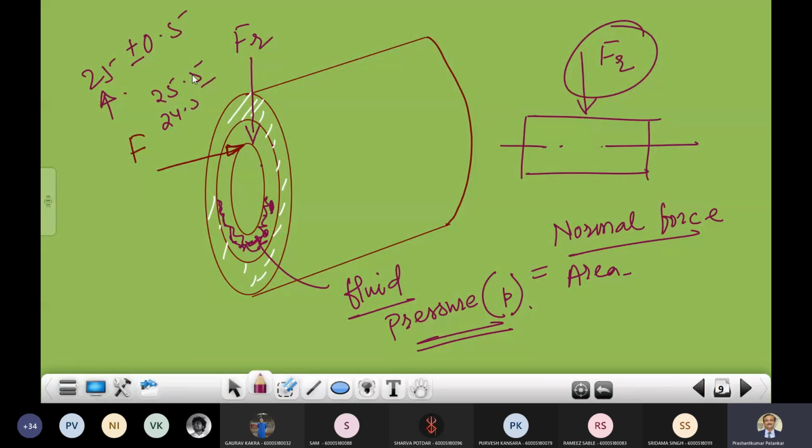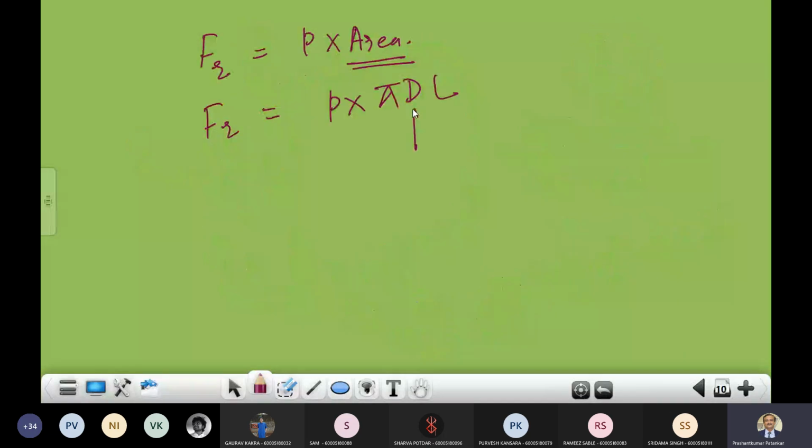Are you understanding? This is how we specify the tolerance in general. So for your shaft and that of your bush, the inside diameter or basic size of the shaft and that of your bush are the same only, and this particular clearance is always taken in microns, and for that reason here I use the same notation. Do you understand why I have used the same? Now I hope I'm clear.